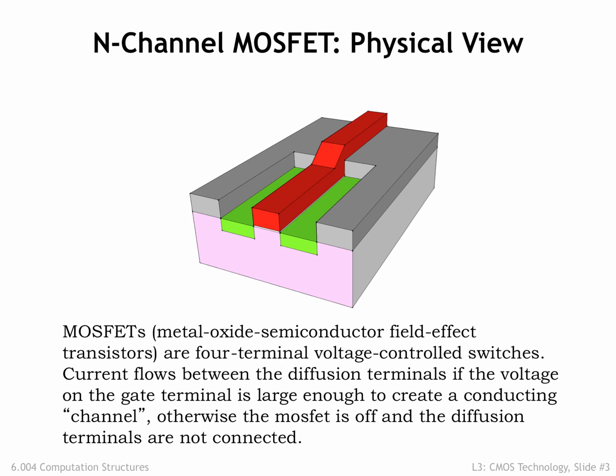The star of our show is the metal oxide semiconductor field effect transistor, or MOSFET for short. Here's a 3D drawing showing a cross-section of a MOSFET, which is constructed from a complicated sandwich of electrical materials as part of an integrated circuit. So called because the individual devices in an integrated circuit are manufactured en masse during a series of manufacturing steps. In modern technologies, the dimensions of the block shown here are a few tens of nanometers on a side. That's 1/1000th of the thickness of a thin human hair.